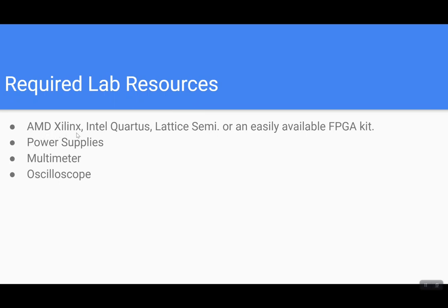I think having an FPGA kit is sufficient, but these other three things are good to have for a nice lab environment, because most of our labs will be focused on only using a particular selected FPGA kit, and most of the time the kit comes with the power supply, so you don't need a power supply or multimeter or oscilloscope, because we can implement a digital logic analyzer within AMD FPGAs or the AMD Xilinx toolchain.